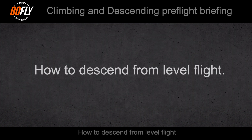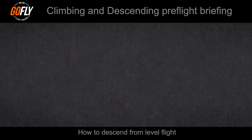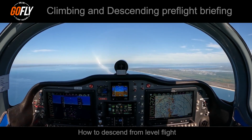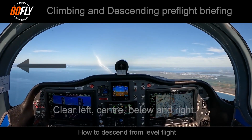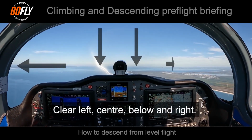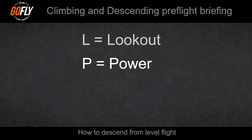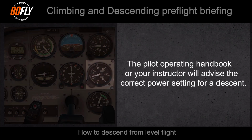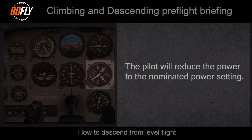We'll now demonstrate how to descend from level flight. The acronym for a descent is LPAT. L is for lookout. Before commencing the descent, it is important to look out for any aircraft. We'll do this by clearing our left, center, and below, and right. P is for power. Depending on aircraft type and what the pilot operating handbook stipulates, the pilot will reduce the power to a nominated power setting.